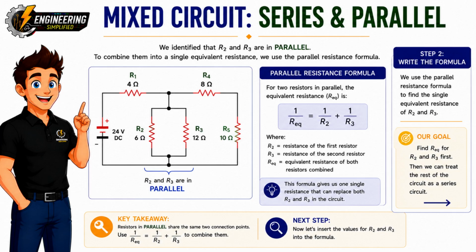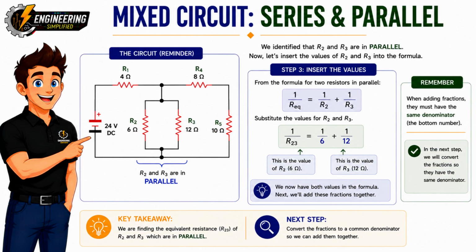So we've successfully broken the circuit into 3 simple sections. R2 and R3 are in parallel. R4 and R5 are in series. R1 is in series with both of those sections. This is the key idea when solving mixed circuits. Always identify the series and parallel sections first, simplify them one at a time, and the entire circuit becomes much easier to analyze. Next, we'll calculate the equivalent resistance of the parallel branch formed by R2 and R3.